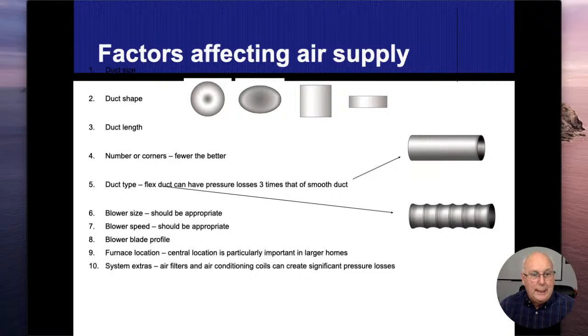So if I want to say that I have slow airflow coming out of one ductwork, and I could show that I have 40 cubic feet from this one, 35 from that one, 41 from this one, 38 from this one, and 4 from this one here, and I could show numbers on each one of them, I think that really sends the message home that I have low airflow coming out of this one for my clients, in case they want to negotiate these things.